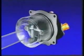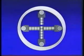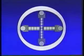The rotation of the inner cam pushes the plungers via the rollers, which effectively pumps the fuel. The use of the two opposing plungers in this manner minimizes the drive torque fluctuations, which makes for quieter operation.